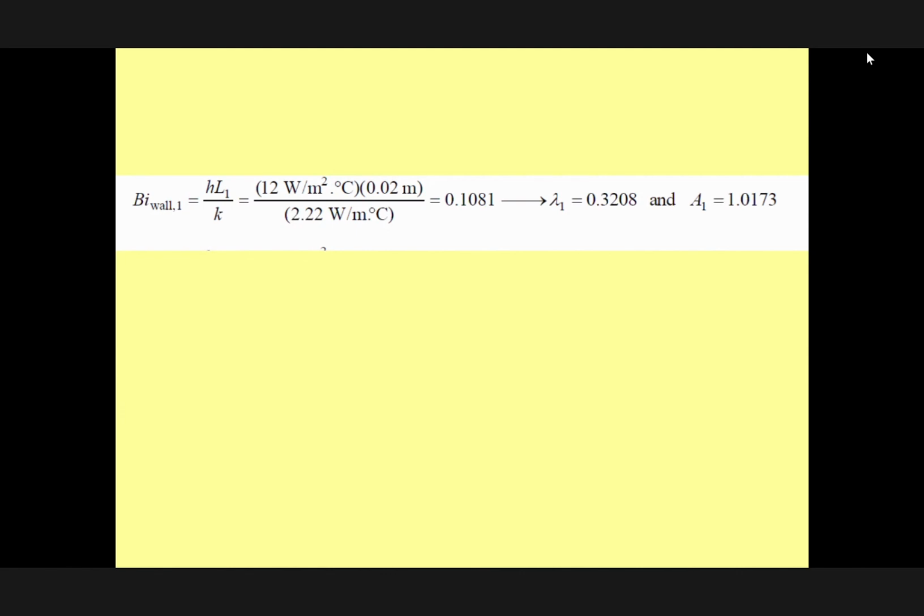Now, look at the temperature on the surface here. The heat transfer to this point is from this side and from this side and from this side. Therefore, there is conduction coming from these two different sides to this point. But if you look at the surface at this corner, there is less conduction coming from the other side, because here and here are more exposed to air.